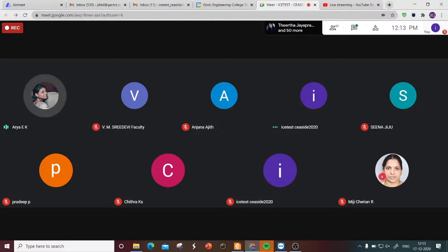On the research side, mostly the researchers have done their work on coated rebar systems. That is not a protection mechanism, but a corrosion prevention mechanism for newly constructed structures. We have a concept that if the steel rebars are coated properly with commercially available coating systems, then the chloride ions from the external environment won't reach the rebar.